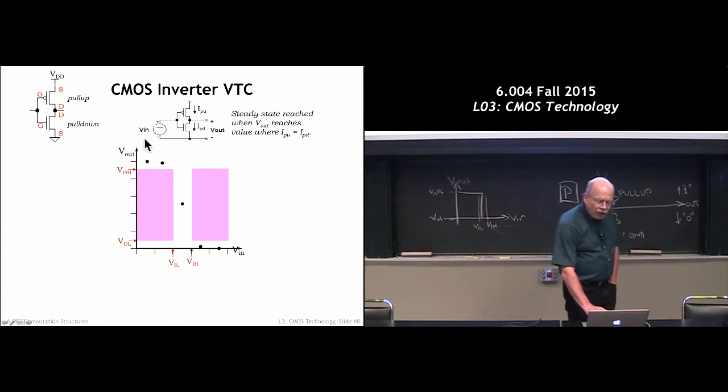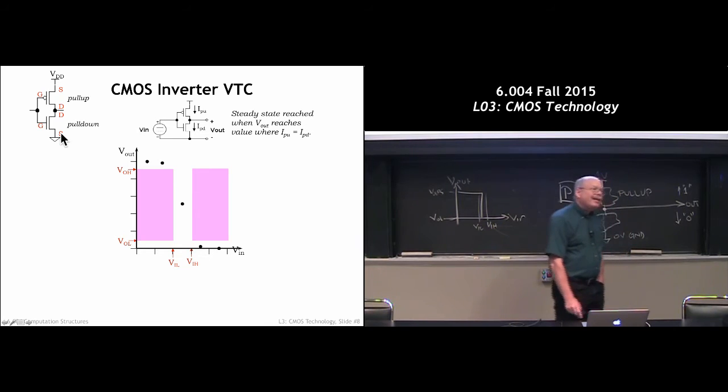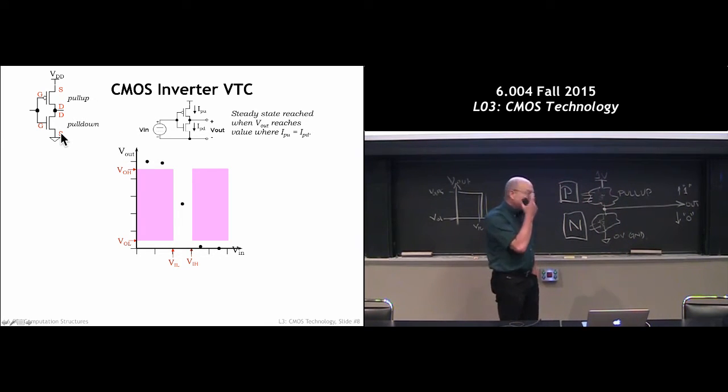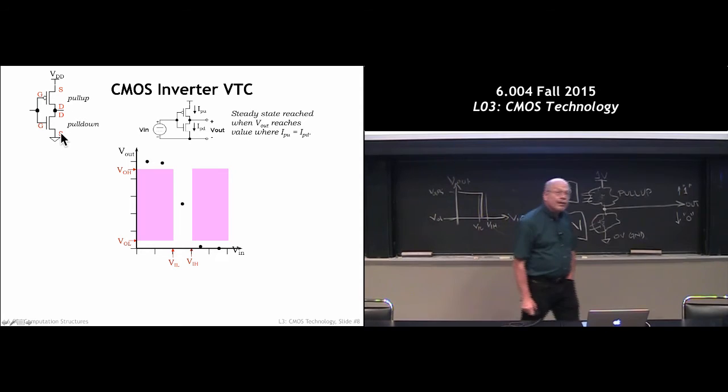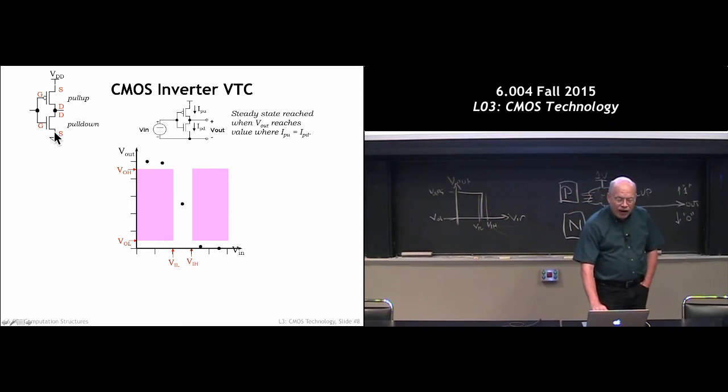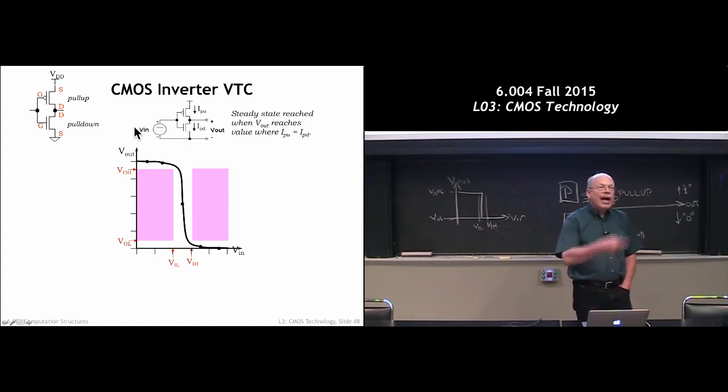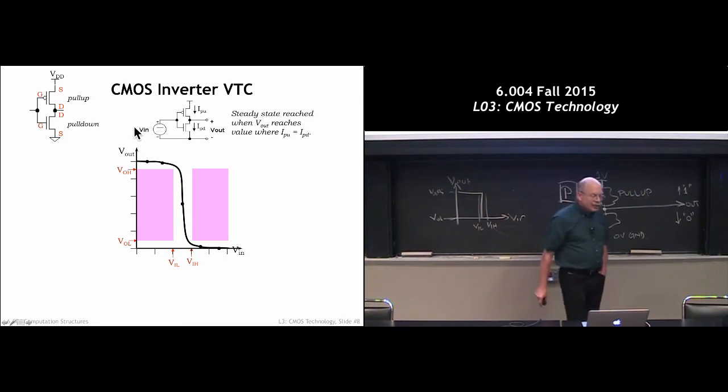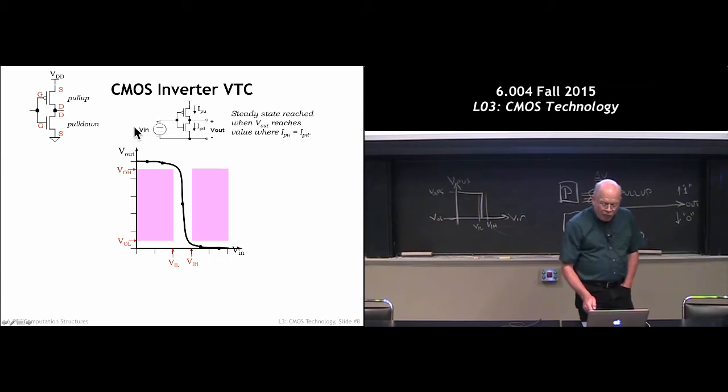Okay. So let's look at our first circuit. This is a very simple device. This is actually a transistor schematic for an inverter. Right? So this is a device that when I put in a low voltage, I get out a high voltage. The output node is high. And when the gate voltage is high, I get a low output voltage. So let's see how this works. First of all, I can set up this experiment and run it. In fact, you do that in lab 1. You use our little circuit simulator to figure out how this circuit works. But let's conceptually think about what's happening.